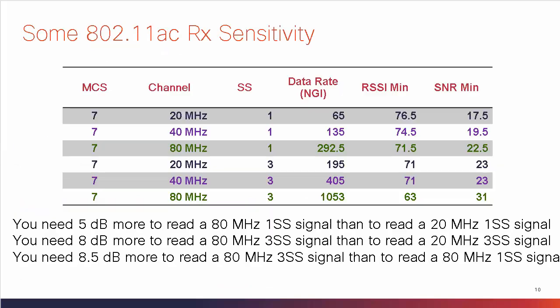So what does that mean for your transmission? Well, in the 802.11 AC amendment, there are some minimum performance figures that vendors must comply to. That is to say, what kind of signal and what kind of signal quality do you need to be able to receive a transmission in 20 MHz, 40 MHz, 80 MHz, etc. Those are minimal performances and most vendors do better. Cisco does much better. But what is interesting is that the same logic will be seen in the theoretical minimum receive sensitivity and in the vendor practical performances. They may be better, but they follow the same logic.